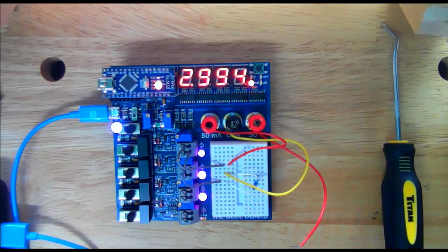So my guess is that was a 1K resistor. I didn't check, I just pulled it. But if we applied 2.995 volts and we are now reading 2.994 milliamps of current, well, I probably just connected a 1K resistor in series to this 3 volt supply. Now one thing to note, these supplies are isolated, so we can play whatever games with them we want.